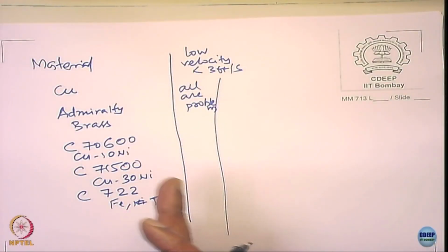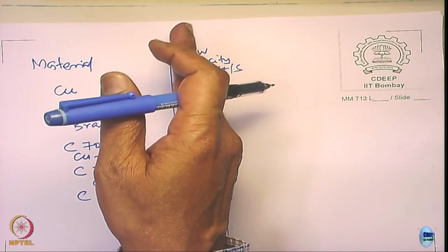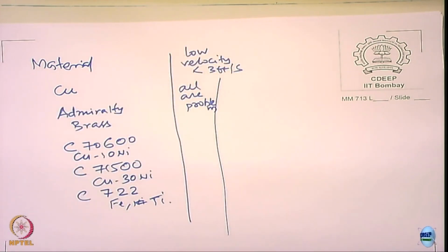See, most of the process fluids might have some kind of particles, second particles, dispersed particles. Sometimes in heat exchangers, if you see water, maybe some foulant, when the velocity is very low, then what happens? They start depositing on the surfaces. It's not an erosion corrosion problem, it is another kind of problem that you are going to get, okay. And so you normally have problems in these cases.